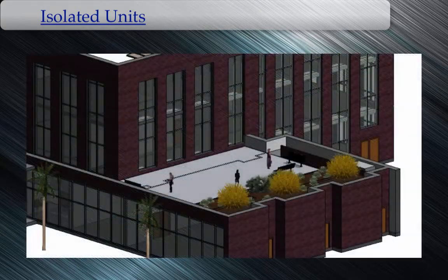Isolated units. Per the client's requests, the computer room's cooling systems were scheduled to run 24 hours a day. Given the sensitivity of data in the rooms, located on the 1st and 3rd floor of the building, we selected to utilize direct expansion cooling systems. Direct expansion units required no ductwork and, given their size, did not need a large square footage for storage. They were also powered by electricity and were completely independent of the active chilled beam system.